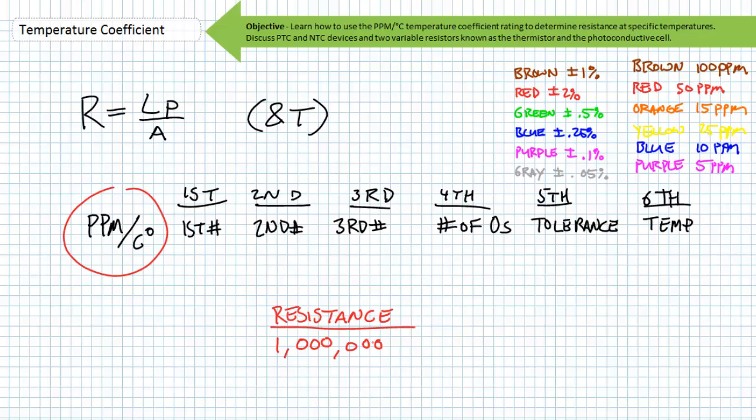If, via the temperature coefficient, resistance was to change a number of parts per million per degree Celsius change, you would just divide this nominal or nameplate resistance into a million parts and multiply it times the ppm per degree Celsius temperature coefficient times the change in temperature in degrees Celsius. Every time the temperature changes by a degree Celsius, the resistance will change by this much.